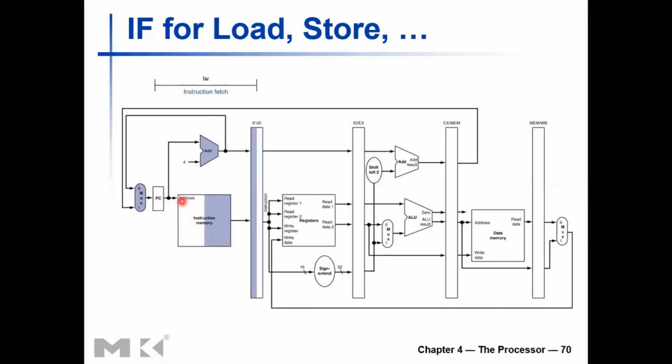Okay, so the instruction memory reading also will take some time. You can assume the reading is done combinationally or asynchronously, not synchronized to a clock edge. So after the program counter write delay and read delay, your instruction memory read delay will happen. And after that latency, your new instruction will be available at the output of the instruction memory.